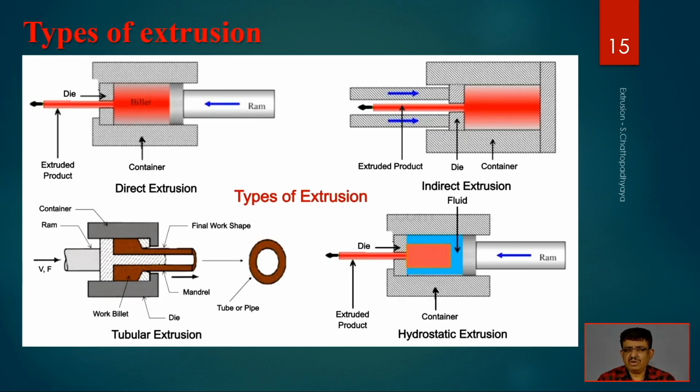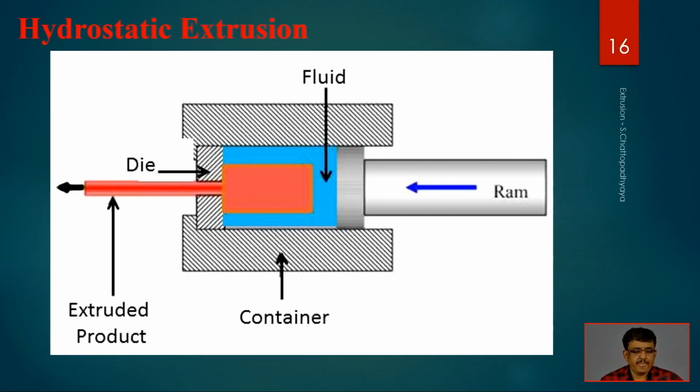So the product will be balanced, with no jerk, and misalignments and other problems are not there, as the pressure comes uniformly from all directions, and the product and alignment will be great. So this is called hydrostatic extrusion. We are using an agent in between the raw material and the plunger in order to give a very uniform level of pressure.